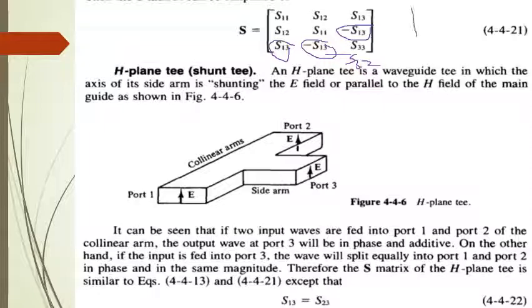You recollect that diagram? Recollect the diagram of E-plane? I hope you remember it. Right? This was 1, this was 2 and 3. So I am trying to tell you this. Here, according to S matrix of three-port network, here it was S32. S32 can be written as S23 reciprocal network, but S23 is equal to minus of S13. That is substituted. Right? Here also it was what? S31 reciprocal. You wrote it as S13. Clear? Here it was what? S21 reciprocal S12. I hope you got these definitions.